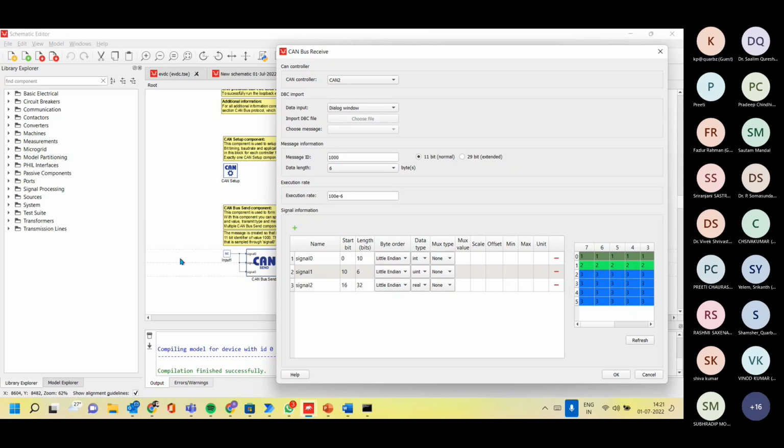Now regarding this, if in some network the CAN high bus has a speed like 500 kbps and CAN low has 200 kbps, then all the ECUs connected to the CAN have to be configured to 200 kbps.